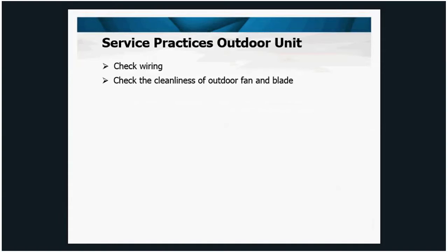You should also check your blade. And the main thing I want to check for on the blade, not so much cleanliness, because blades frankly don't get that dirty, it's for cracks. Because if a crack develops in the blade, it will continue to get worse and worse as that blade flexes when it runs. The crack will get worse, and when it reaches the edge of the blade, it can cause that blade to peel up